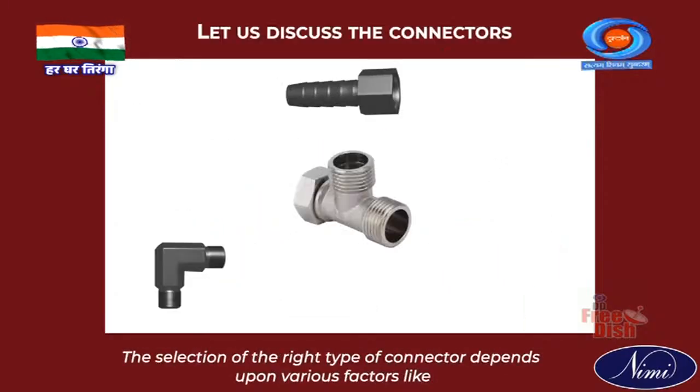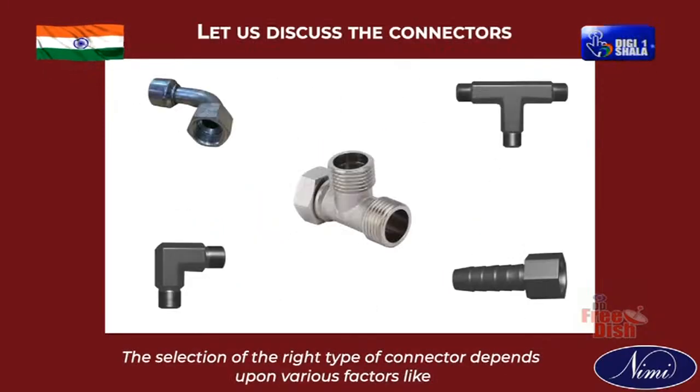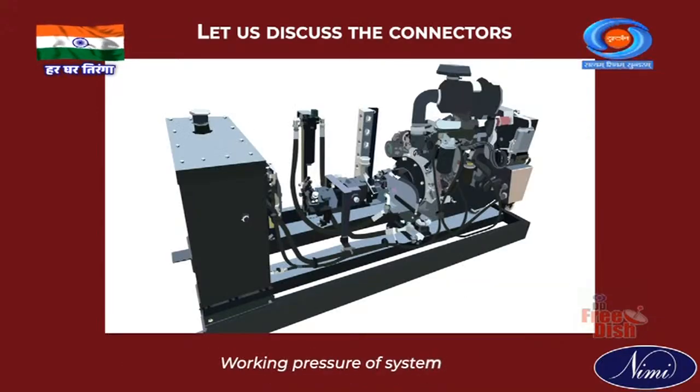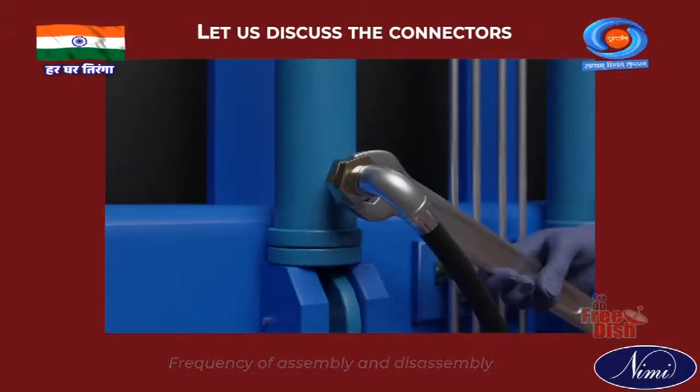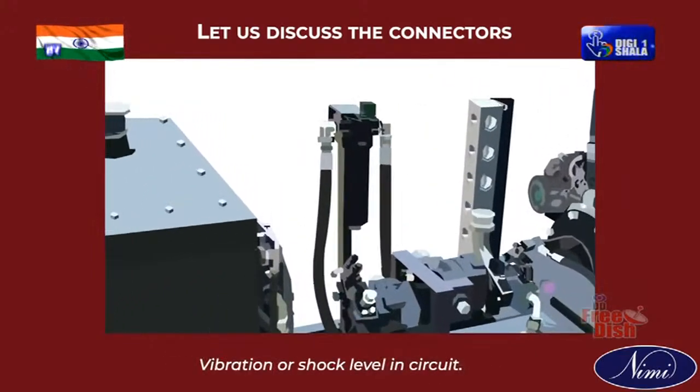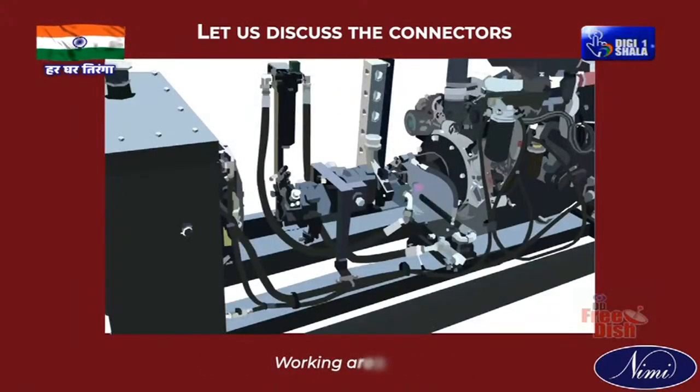The selection of the right type of connector depends upon various factors like working pressure of the system, frequency of assembly and disassembly, vibration or shock level in the circuit, and working area.